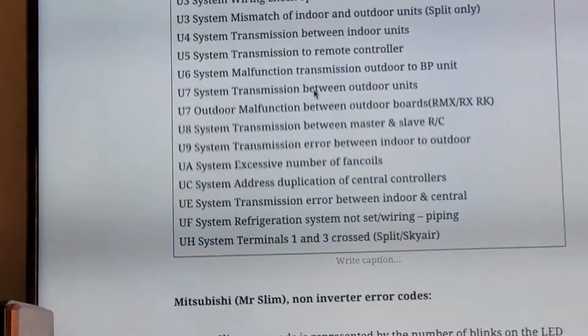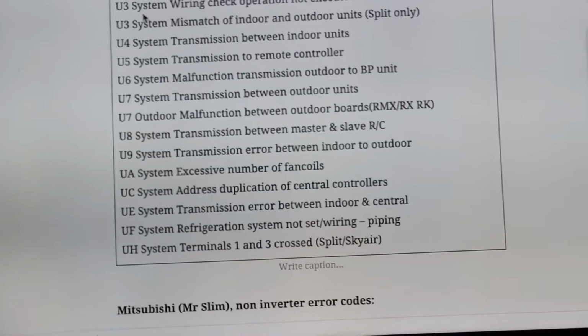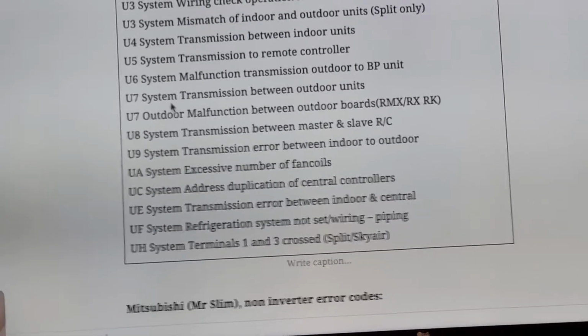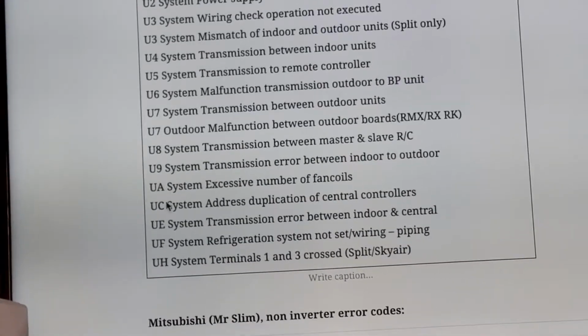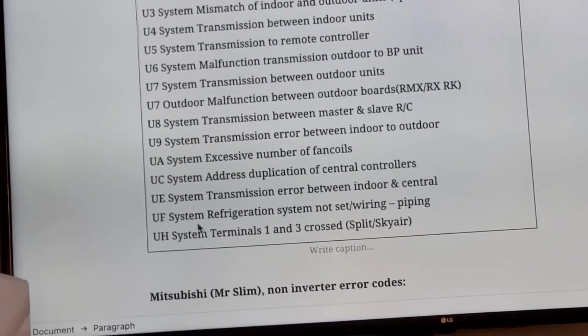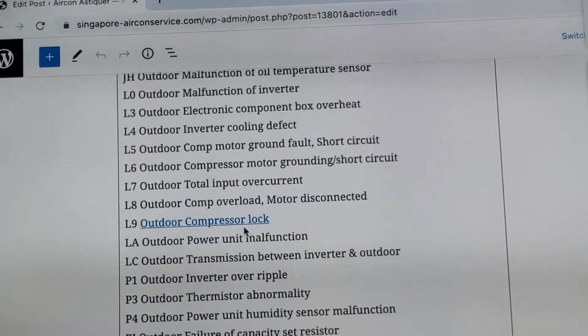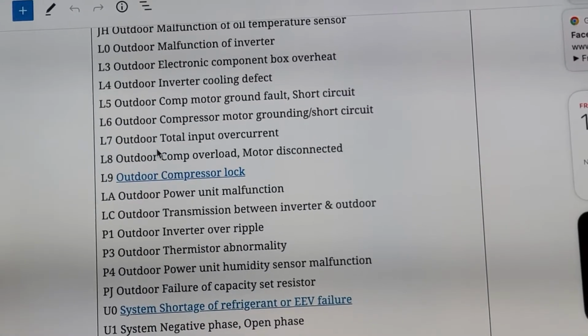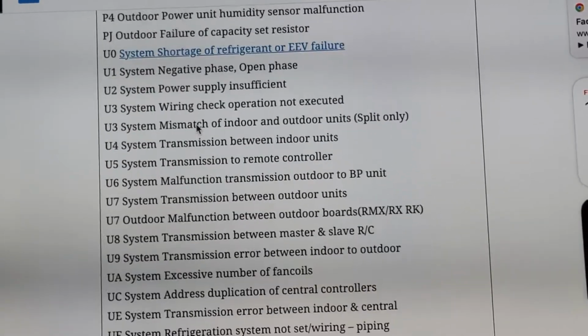The main grouping, the U, if you look at the malfunction codes carefully, seems to be all related to the system power supply transmission error, with an exception of a refrigerant shortage problem. So they do group it in such a manner. Some are temperature sensor, fan motor, etc. But usually it's a temperature sensor error. That's the common thing. So okay, back to this.